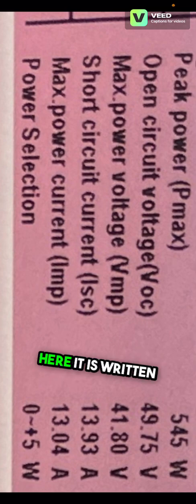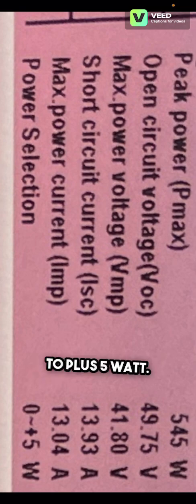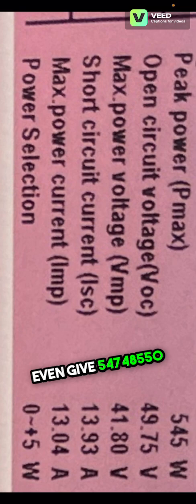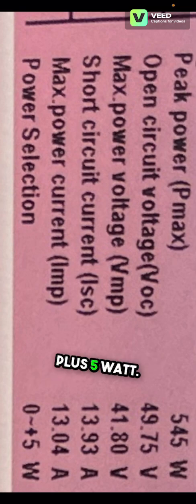And another one here, it is written power selection 0 to plus 5 watt. This is a very good point. It means this panel will never give less than 545 watts. Sometimes it may even give 547, 548, 550 watts. That's why we call it a positive tolerance panel, plus 5 watt.